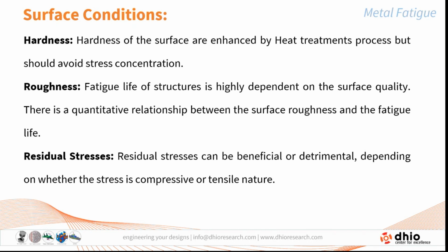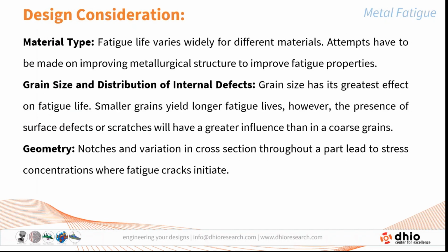And then on the surface, there are residual stresses, which can be beneficial or detrimental depending upon whether the stress is compressive or tensile. If it is compressive, it is beneficial. If it is tensile, it is going to be detrimental. That means if a tensile residual stress is induced in the component, then the life of the component can be expected to be very low. If it is subjected to residual compressive stress, one can enhance the fatigue life of the component.